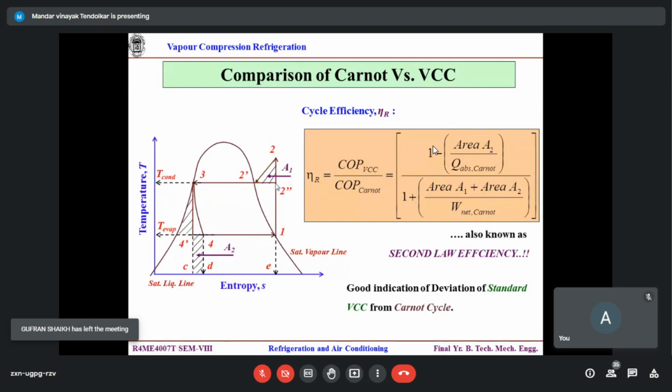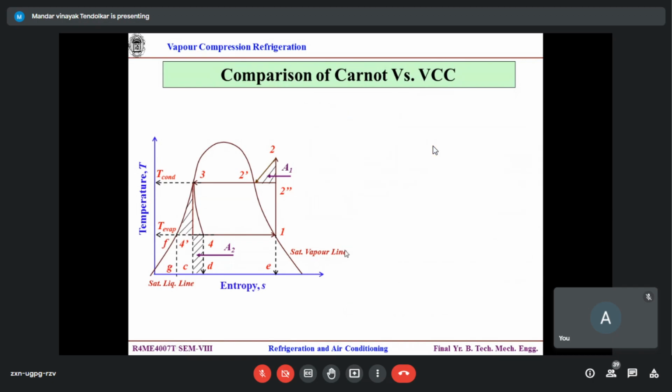So somehow if I could stop over here and start the isothermal heat rejection, this is isobaric heat rejection, so that is why pressure. If I follow this horizontal line entirely, it will be isothermal, correct? So I can execute the process as close as possible to the Carnot, and my second law efficiency will be, let's say, 90% or anything closer to that of the Carnot, correct?